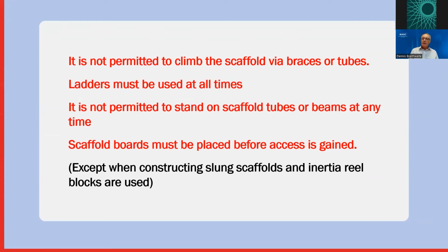Now, it's not permitted to climb the scaffold via the braces, the tubes. The scaffolders must use ladders to climb at all times. They've got to be tied or footed to make sure that they're safe. It's not permitted to stand on scaffold tubes or beams at any time. Scaffolders must place scaffold boards and stand on them so they've got a firm platform.